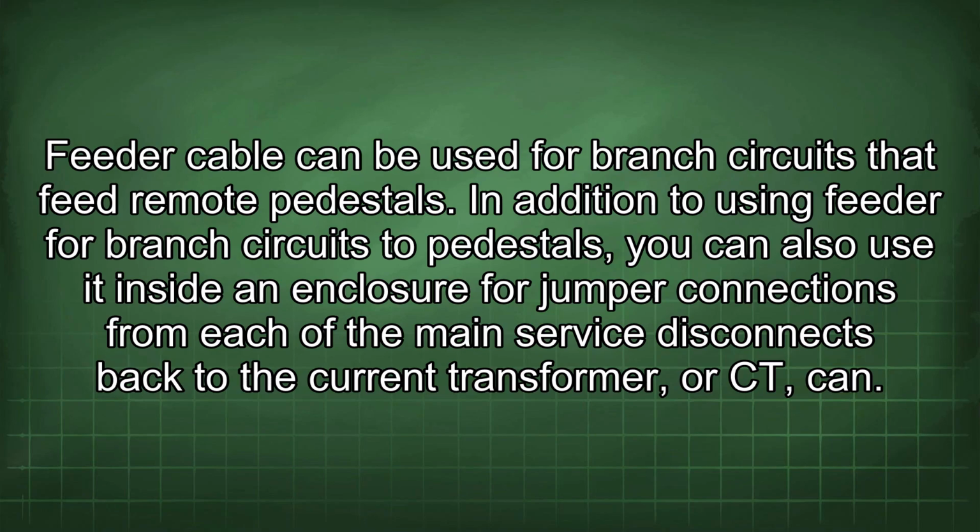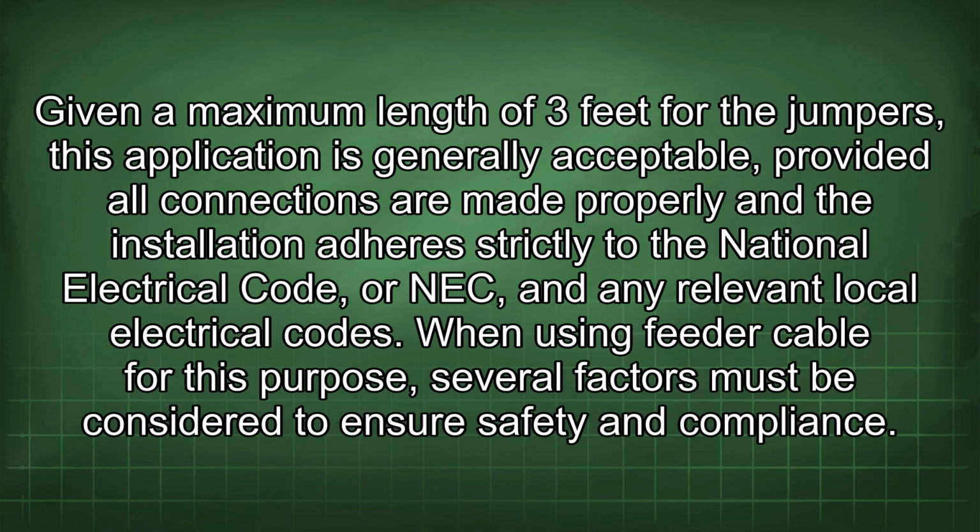Feeder cable can be used for branch circuits that feed remote pedestals. In addition to using feeder for branch circuits to pedestals, you can also use it inside an enclosure for jumper connections from each of the main service disconnects back to the current transformer, or CT can. Given a maximum length of 3 feet for the jumpers, this application is generally acceptable provided all connections are made properly and the installation adheres strictly to the National Electrical Code, or NEC, and any relevant local electrical codes.